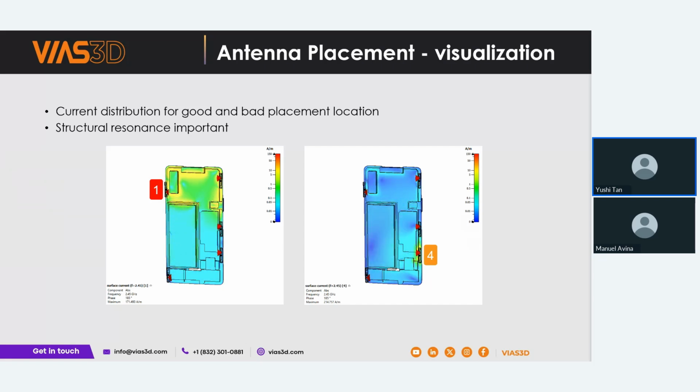So modeling the geometry of the phone is clearly a very crucial step in getting reasonable results. It directly answers the question as to how much we can simplify the model. Sometimes we can make simplifications in certain areas if we know the impact of those details is not so big as to affect our overall performance, and perhaps we can get a faster simulation time. Areas with high field strength are generally more important, so we don't want to simplify the model in those areas too much, because of the high interaction between the fields and the structure.